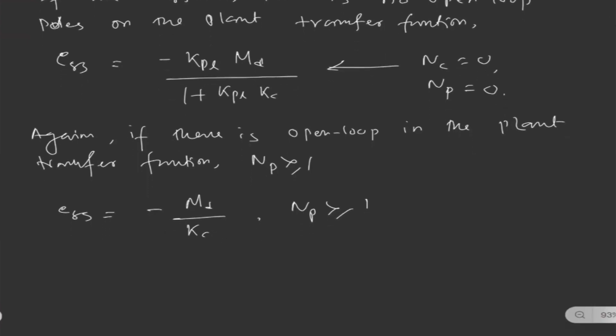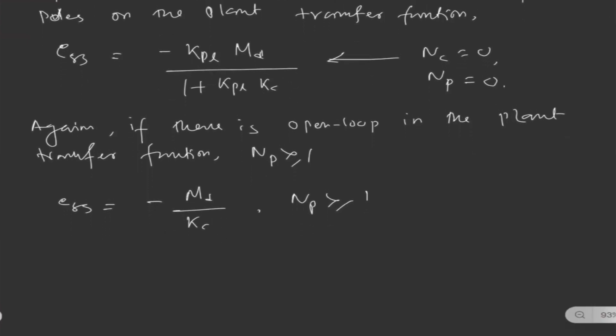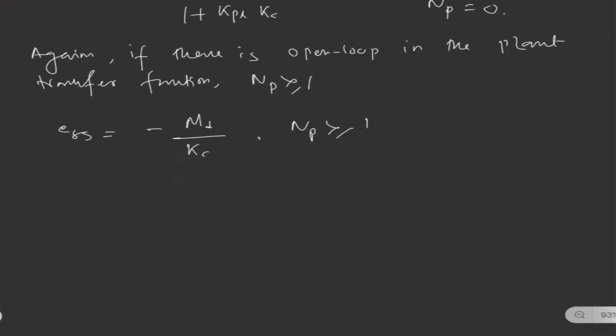This is how we can say how the integrator plays an important role in a control system. If you add an integrator in the controller, we can reject the disturbance effect in the system. So we have both two cases in the control transfer function. If there is no integrator in the system, then how would the steady state error be?